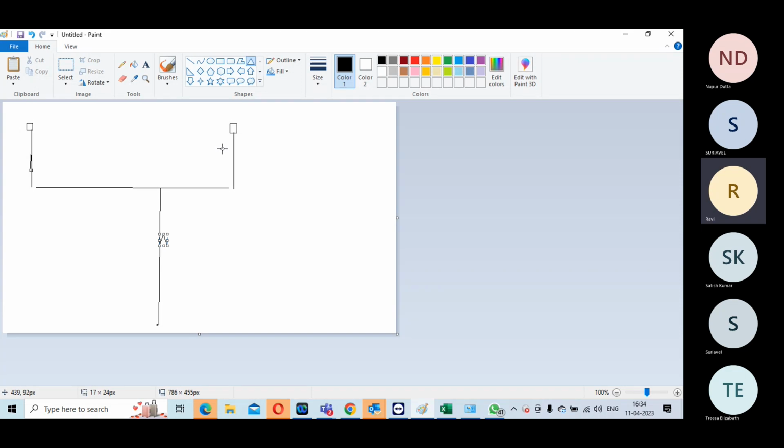If you are creating another PLL for that, then you will be completely delinking these things. They will never be synchronous. They will become asynchronous. Maintain that synchronous property, because these are synchronous paths. Mainly the source latency is not calculated otherwise. The source latency means when the report is generating, from generated clock to source register, latency, network latency, source latency. Yeah, that is the main thing.